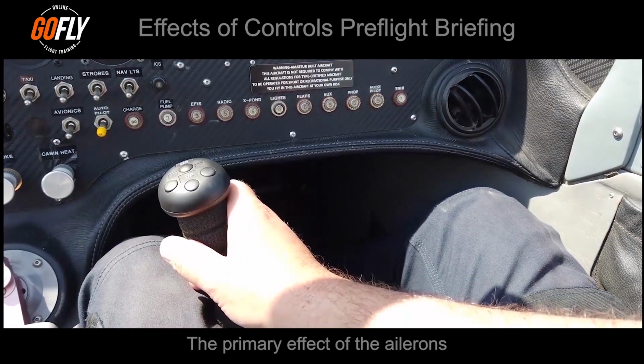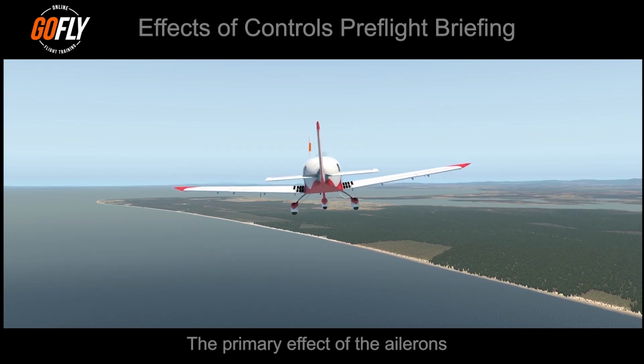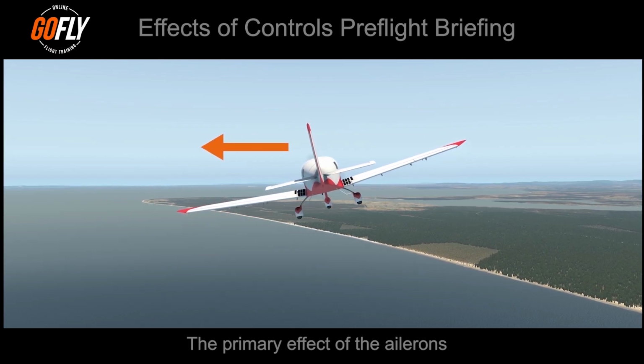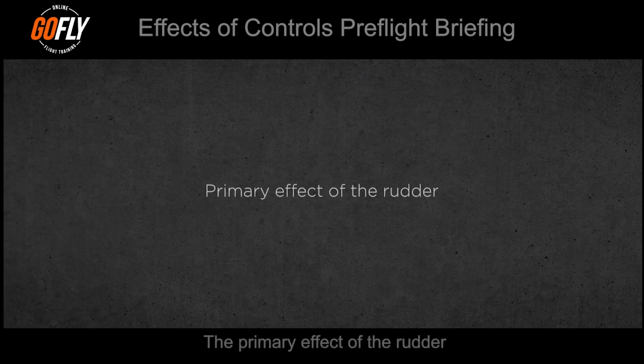When we move the control column to the left, this causes the right aileron to move down, causing an upward force, and the left aileron to move up, causing a downward force, causing the aircraft to roll to the left. The primary effect of the ailerons is roll.